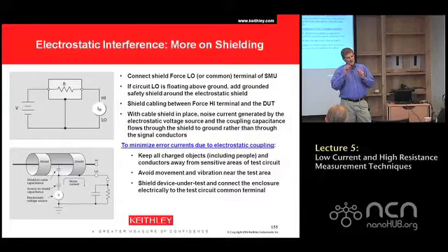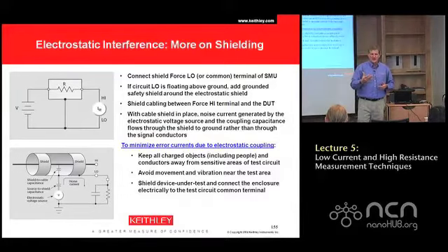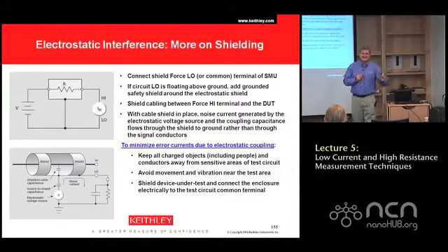But if you disconnect the common of this instrument from earth ground with the jumper link on the back, and then you connect it to an electrostatic shield, there's nothing holding this whole system with reference to earth ground. The whole shield could float up anywhere that it wants to float up to. And what most commonly happens is you get a static shock from it. You touch it, and you get a static shock from it. It's floated off of earth ground. Well, that static shock might be uncomfortable for you, but I can tell you it's devastating for anything that's inside that box, any samples and devices.